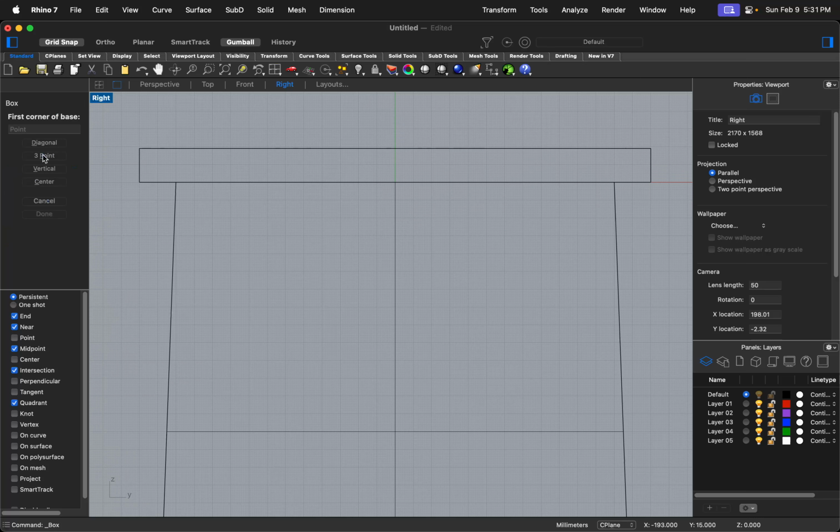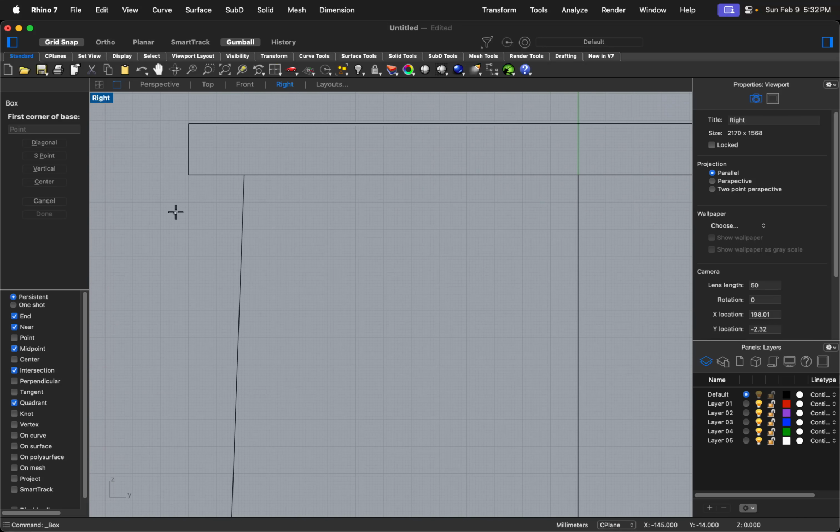To cut the mortise and tenon, you need to have a box as well. In this case, I will just draft a box somewhere from here. And I'm going to give the length a little bit inwards. This one doesn't matter because in the end we are going to cut it out. So I'll just put it somewhere here. But the height I haven't ensured, hang on, I'll just click from here. And then the corner of this, I'll have to observe because the material thickness is 19. So I'll have to ensure that it's about 19 height.